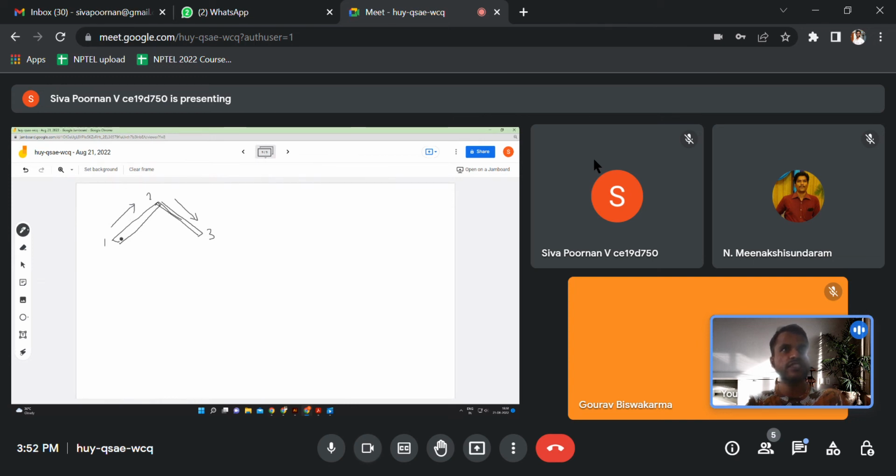So if this is the direction of the member, then theta x is going to be this inclination of the member. Okay, so it will be negative depending upon the direction we take, right? Okay, so we know the stiffness matrix for this member from the usual procedure, whatever we have adopted now. We can also find out the stiffness matrix for this member using the same procedure. Then how do we assemble both of these two?